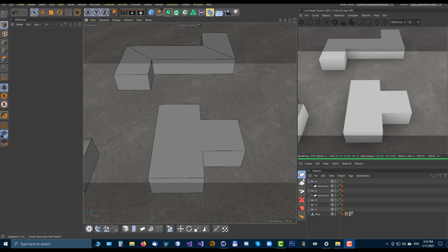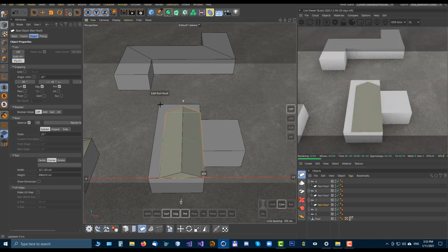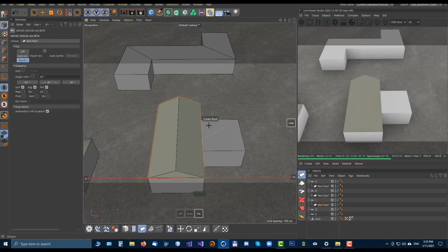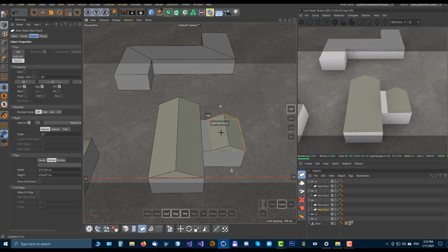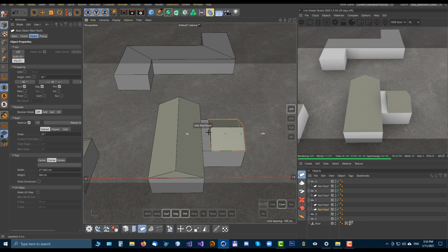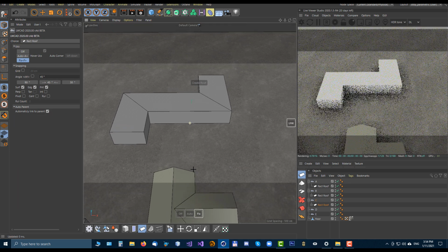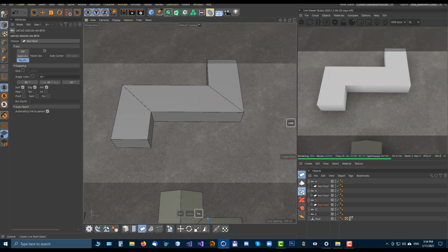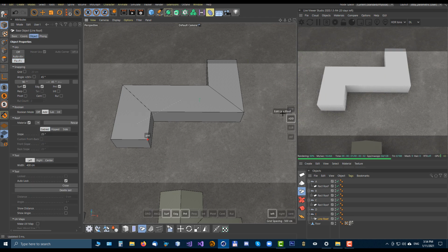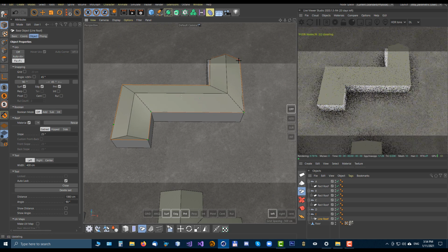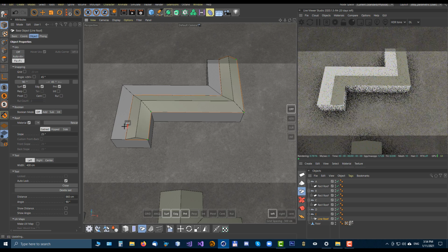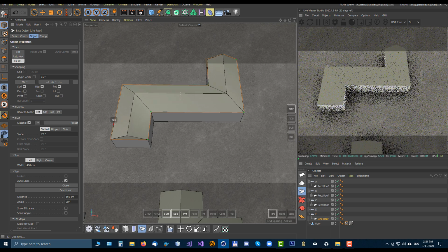In the next example, I will create the gabled roofs. So now change the alignment and set this as a parent and use add booleans. Okay, now add booleans. This is the next example. Here for this I will use the example of the line roof. Disable booleans. So you can see you can very nicely use all these handles to fit the object.